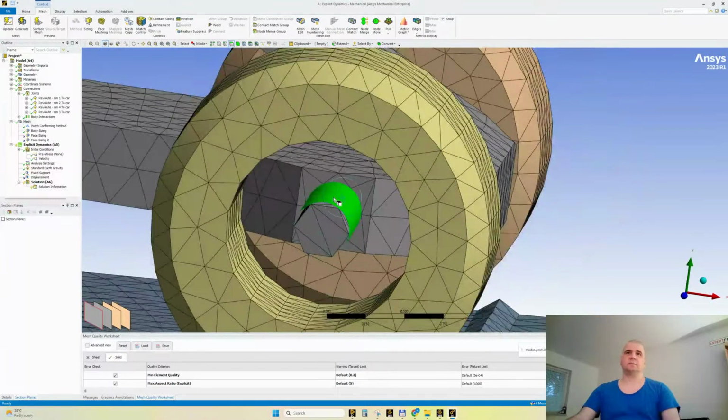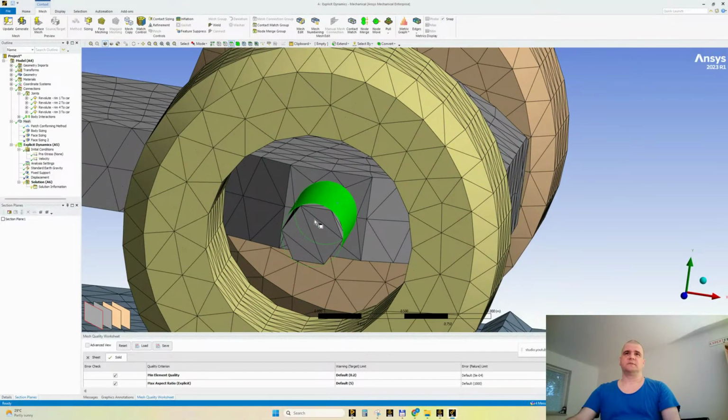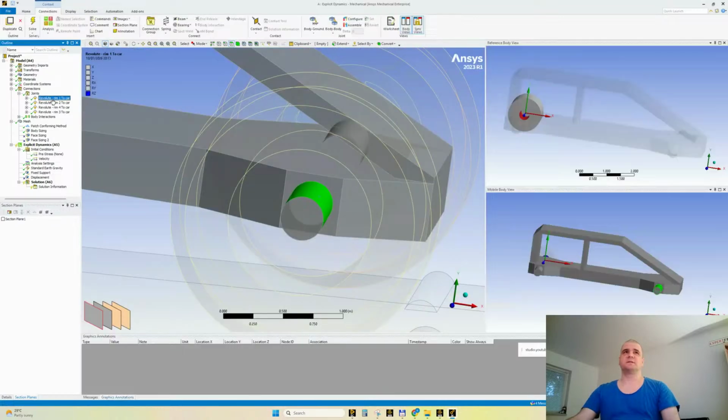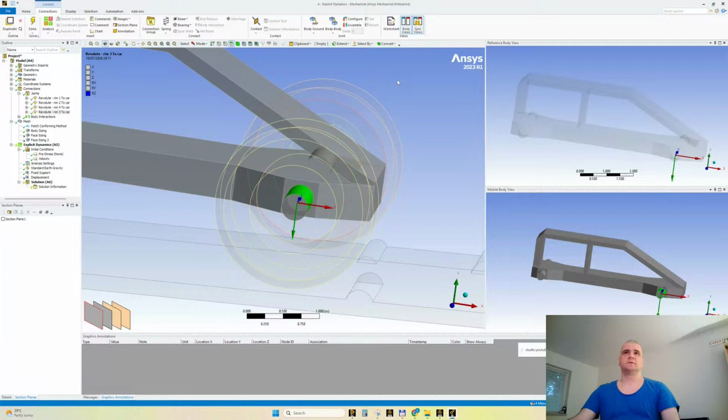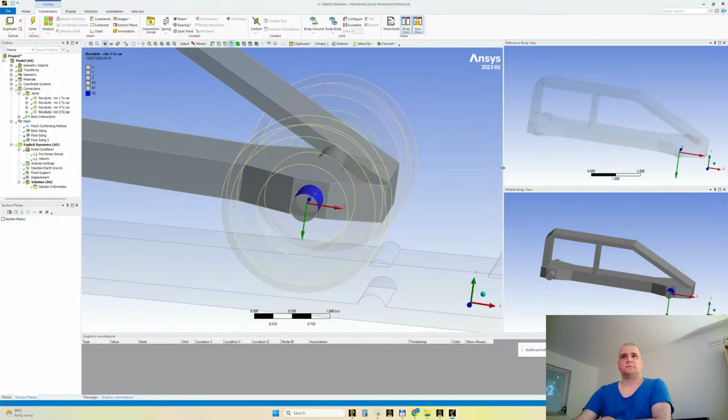If I click here, it's a perfect cylindrical surface, which is used in the definition of the revolute joints. This is the biggest difference between contacts and the joints. Joints are referenced kind of theoretically, using axes and centers of mass, or usually geometrical coordinate systems from the mass of that body or part or feature.